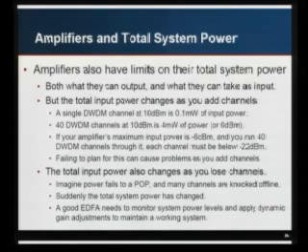So your amplifier, a typical input maximum, may be minus 6 dBm total power. So if you have 40 channels, that means that each channel before you amplify it needs to be minus 22 dBm, which is pretty low. You have to really take this into account when you engineer a complex amplified system.